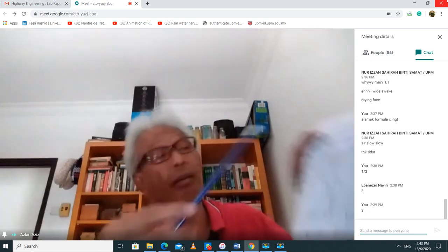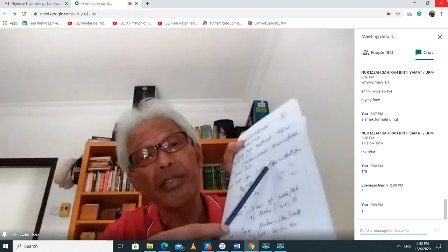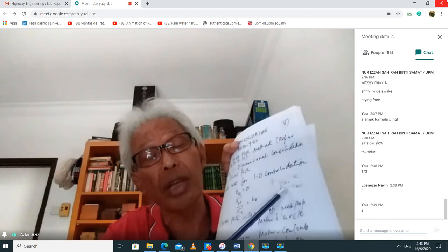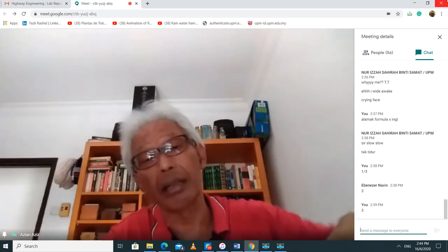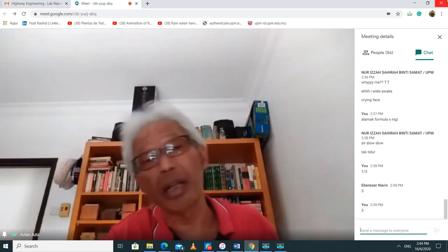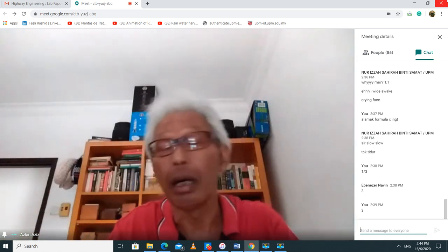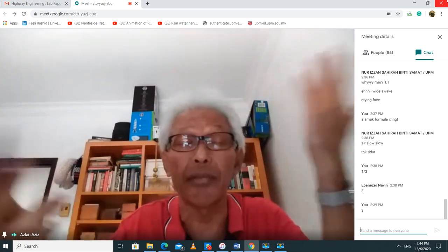So here's my element again. It is subjected to some sigma V and to some sigma H. I can calculate the sigma V. I can calculate the sigma H. The sigma H, if it is an active condition, is related to the sigma V by K sub A.